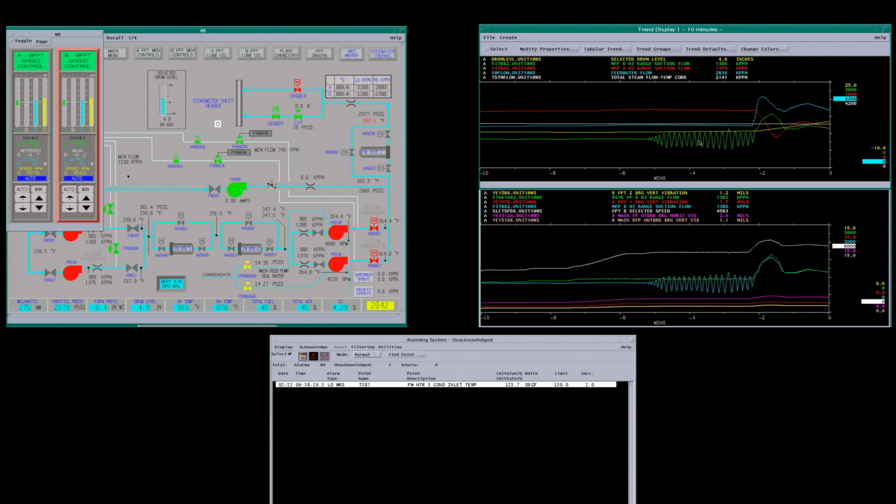This one here is in a bad range for the pump. Design specs, usually at 2900 will drive up real fast to around 4800. Today we just went a little slow through here to demonstrate this. Anyhow, that's feed pump cavitation. Don't do this in real life. Have a good day.